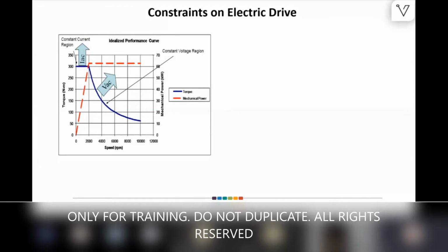That is the average, because that is the rating we can call, and it is not actually a stagnant point. It is variable, but somewhere we have to rate. So typically OEMs go for the 60%, 70% SOC region, and at that point see what C rate we have, what current we can get from the battery as a discharge, and what voltage we have at that particular discharge. For example, at peak we discharge close to 3C, 4C kind of current, so 4 times the rated 1C of the battery. Say for example 100 amps, that 100 amps is converted into torque, which is directly proportional to the torque.